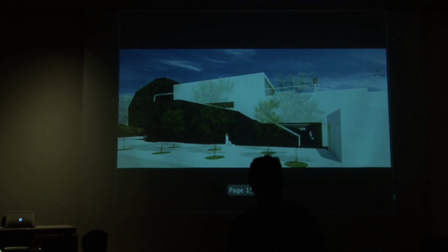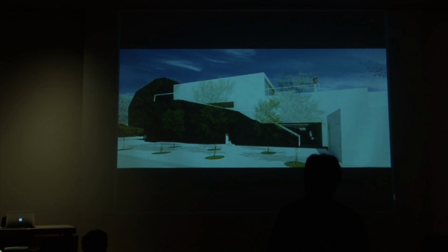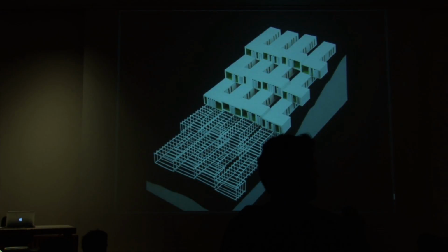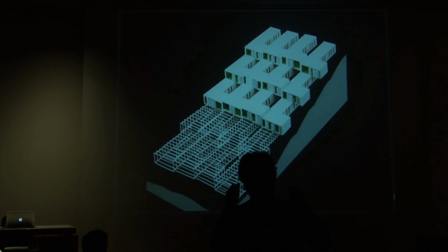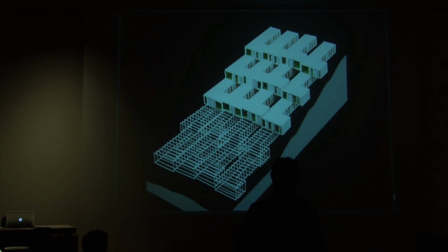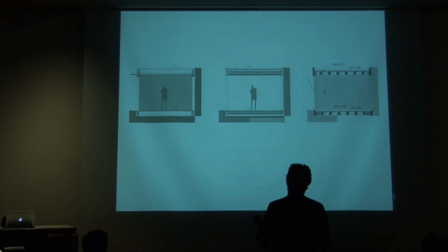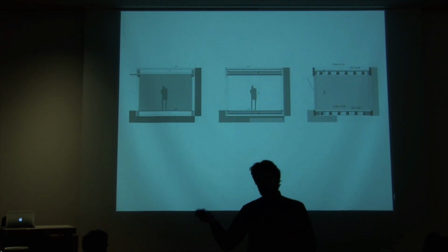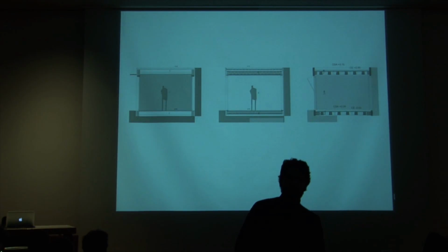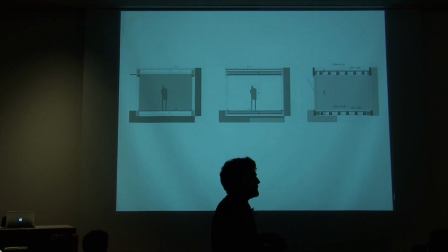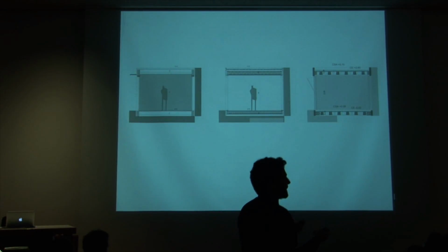We plan to build that construction with wood. We thought that it was quite interesting that this carpet would be very light and would not have a big influence on the site. So we analyzed it, but unfortunately it was too expensive because of acoustic reasons. So it was not a problem for temperature, but the neighbors that were one on top of the other with this light construction, it turned out to be expensive to solve it with the same system.